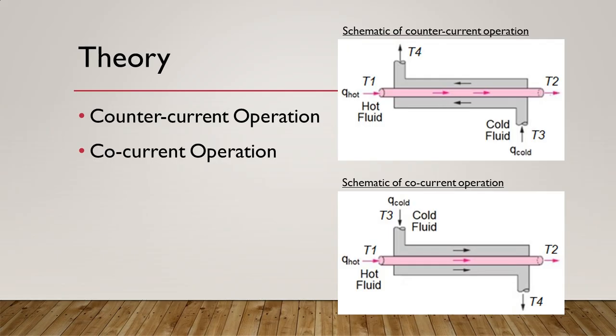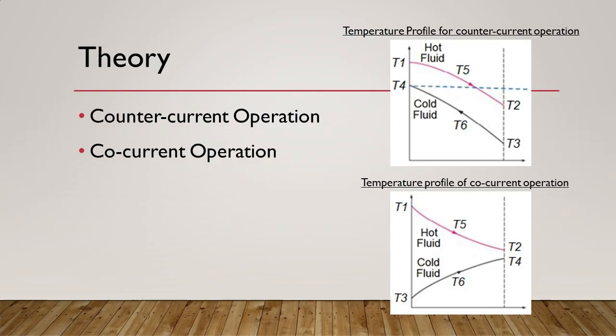The water flow direction can be changed in our instrument, so that the flows are in the same direction, that is co-current operation, or in opposing directions, that is counter-current operation. In normal operation, hot water from the heating tank and pump passes through the hot-out braided hose and self-sealing coupling into the inner stainless tube. It then flows through the heat exchanger and leaves via the hot return braided hose. Cold water flows from the cold-out hose through the annulus between the clear plastic tube and the inner stainless tube.